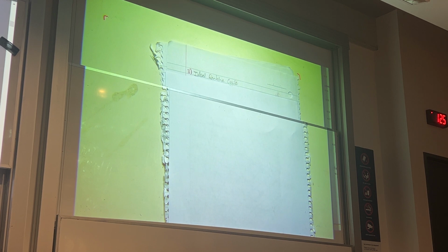So coming back to our graph here, what's important to note is state 1 is a saturated liquid. So we know the pressure, we know it's a saturated liquid, we can find everything we need to know from there. We're given all our properties about state 3, and because we know it's isentropic, using our entropy relation, that's how we can go ahead and solve for all our values at state 4. State 2 is a little tricky, and I'll go through how to solve that. But pretty much we know that our change in entropy will be equal to some relation we've used.